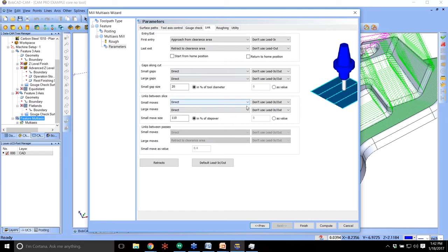So when using these toolpaths, if you're asking questions like, how can I control the rapids? How can I control this? These toolpaths have that option. You can go in and define specifically how you want it controlled, because a lot of the rapids happen because it has to move from one location to another, since the link between a slice or something like that is different. In here, you have those options, and you can set those.